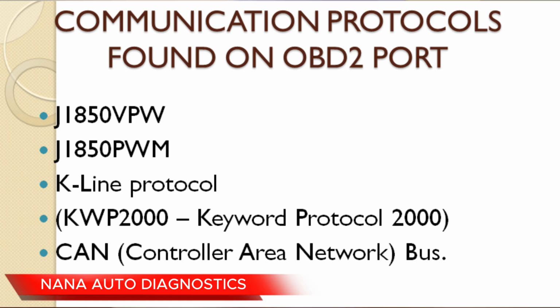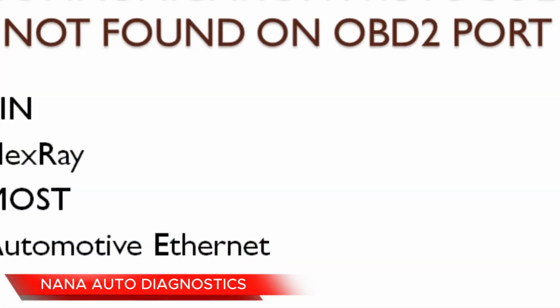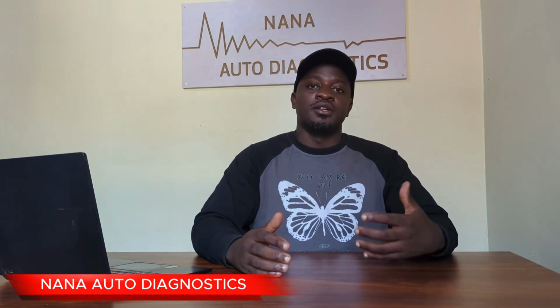So those are the only communication protocols which can be accessed on the OBD2 port. The rest of these protocols, which include LIN, which is Local Interconnect Network, FlexRay, MOST, which stands for Media Oriented Systems Transport, and Automotive Ethernet, cannot be accessed on the OBD2 port because these protocols are mainly used for module-to-module communication.